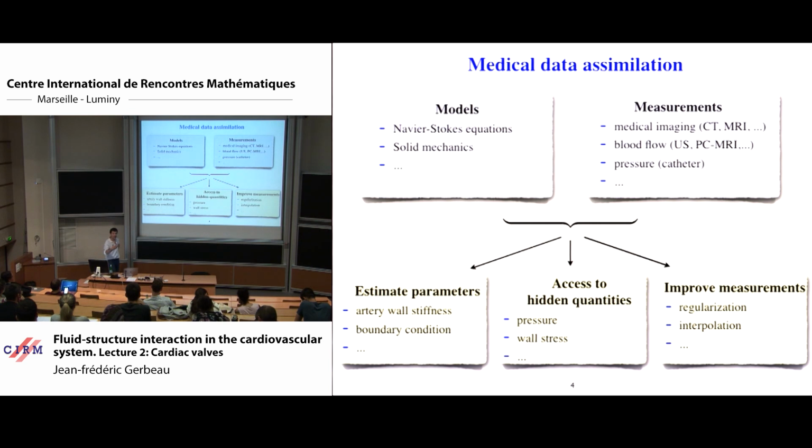Okay, it can be seen as an expensive way to denoise the problem. And when I talk about noise, it's not only the noise on the images, but for example, when you have a velocity field that is supposed to be measured by an image, you can ask yourself if the divergence of this velocity field is zero. It's supposed to be zero. The fluid is for sure incompressible, and in practice it is not. If you take directly the measurements, you do not have a divergence-free velocity. So if you do a mix with a model which enforces the divergence-free velocity from the measurement, then you improve the measurement you have, or you denoise, if you want, the measurement you have.